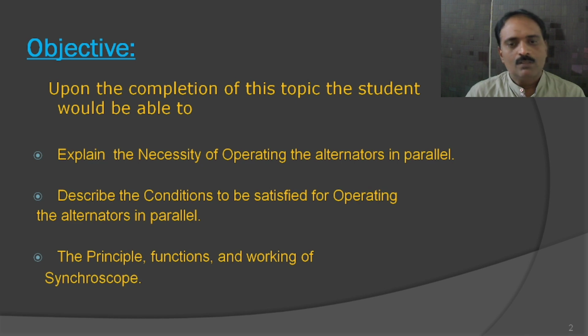And the principal functions and working of Synchroscope. Synchroscope is one of the equipment by which we are going to synchronize the alternators, or you can connect an incoming machine parallel to the bus bars, or another machine which is already synchronized.